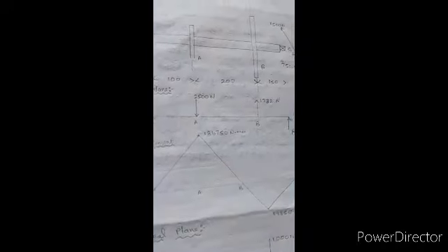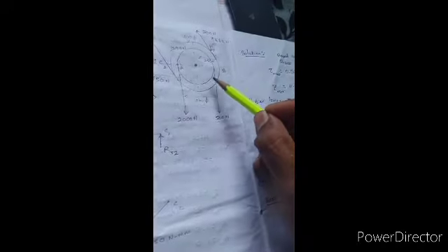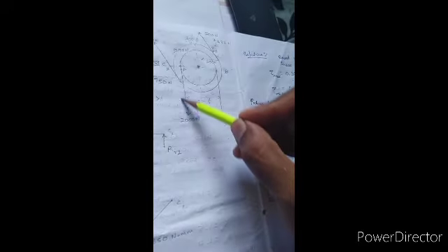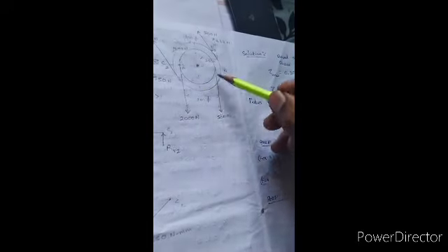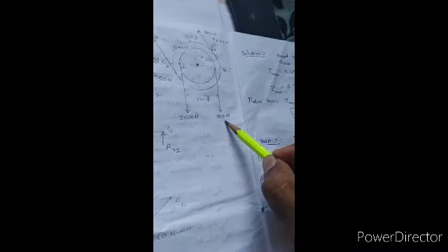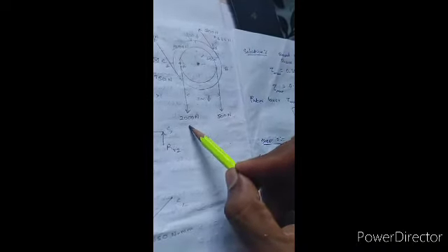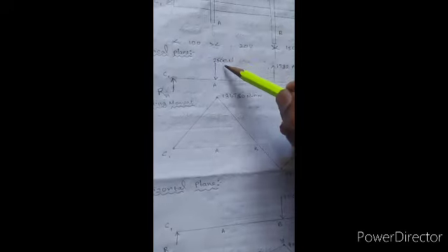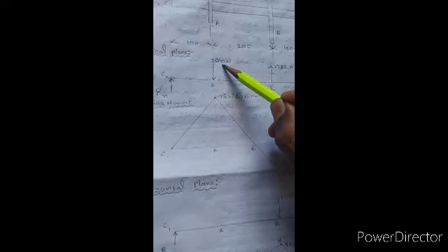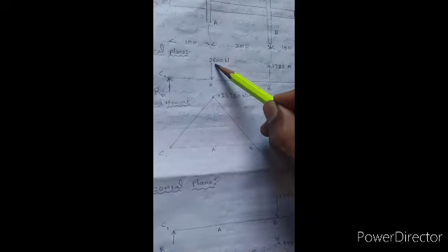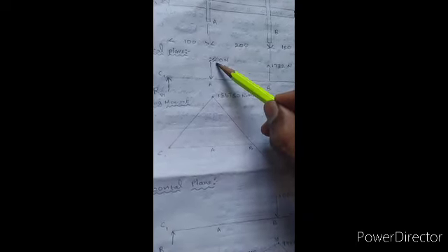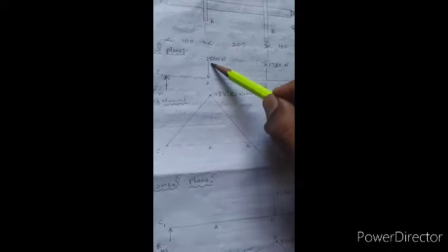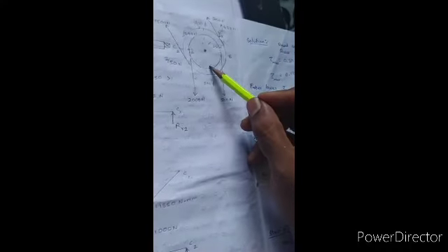Next, on pulley A, see, this is pulley A. On pulley A there is a downward load, no? So there is a downward load, 2000 Newton and 500 Newton. Both loads are downward loads. So add both the loads, 2000 plus 500, 2500. So below pulley A, draw a vertical line and mark it out in the downward direction, because both the loads are acting in the downward direction. 2000 plus 500, 2500 Newton. Right. Next we will go to pulley B.